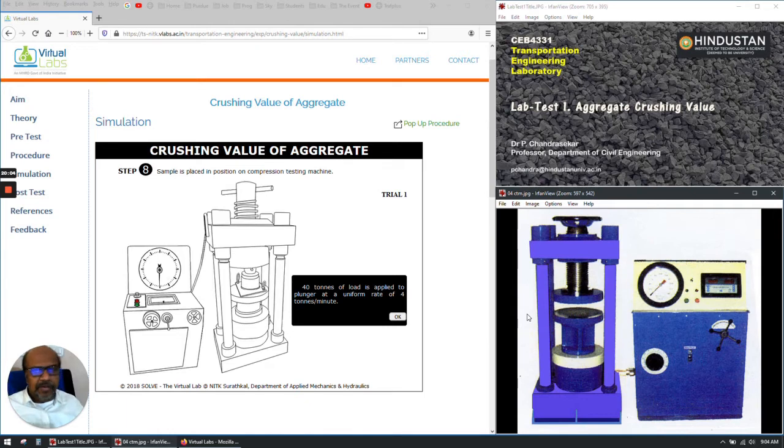A car can weigh 1, 2, 3 tons like that. Maybe a container truck will weigh like 20 tons, 30 tons. But that is actually transmitted to the ground through many wheels, 6, 8 wheels like that. Maybe a military tank, 30 tons, 40 tons, 70 tons. So that might transfer this kind of load, but still 40 tons for a small area is very high. Why do we do that? Because we consider the factor of safety.